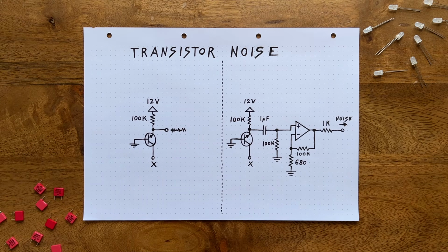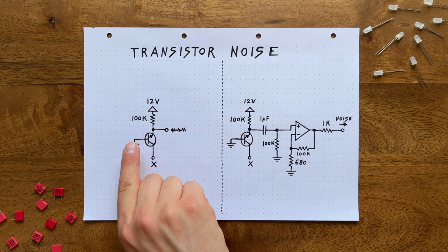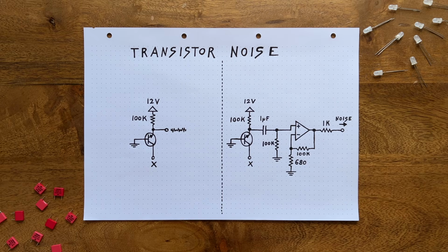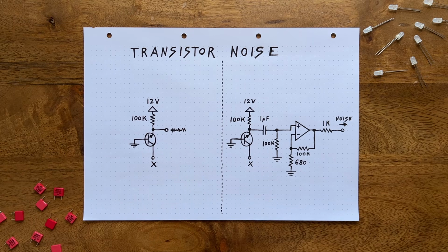But as we increase the voltage significantly above the 6 volts threshold, the transistor will begin to break down, resulting in random bursts of current that flow from the power supply through the resistor into the emitter and out of the base. Now, the more current flows through the resistor, the more the voltage at this point will drop. And that's because the pushing force there is allowed to transform into actual movement of electricity. This way, we convert the random fluctuations in current flow into a voltage that drops below the set supply voltage in both random amounts and random intervals.